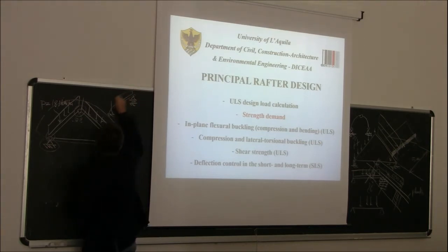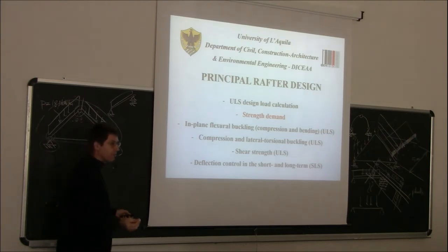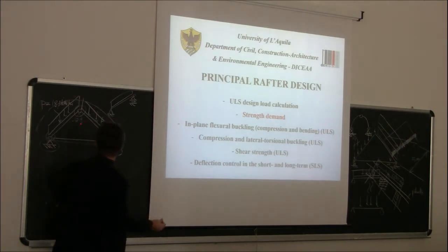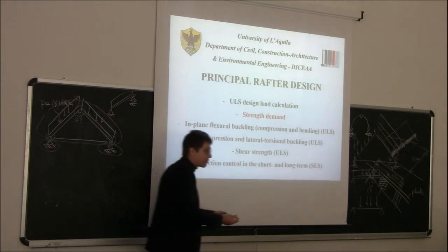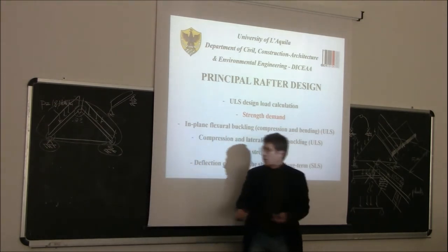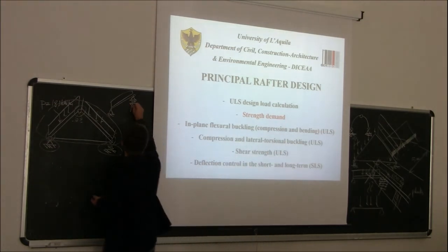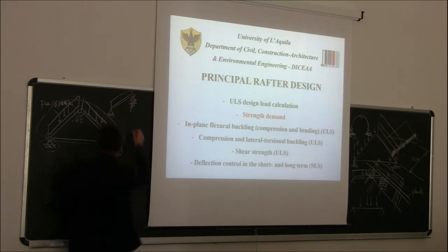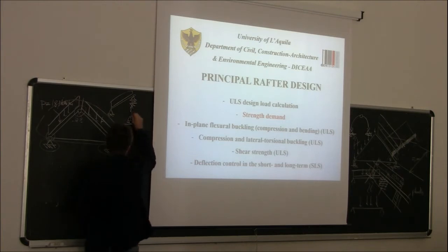A statically determinate beam that I can solve without any problem. Okay? But of course here I have introduced a restraint which is not there in reality. So I will find here a reaction. Then I have to solve the other system. And I will find another reaction there.